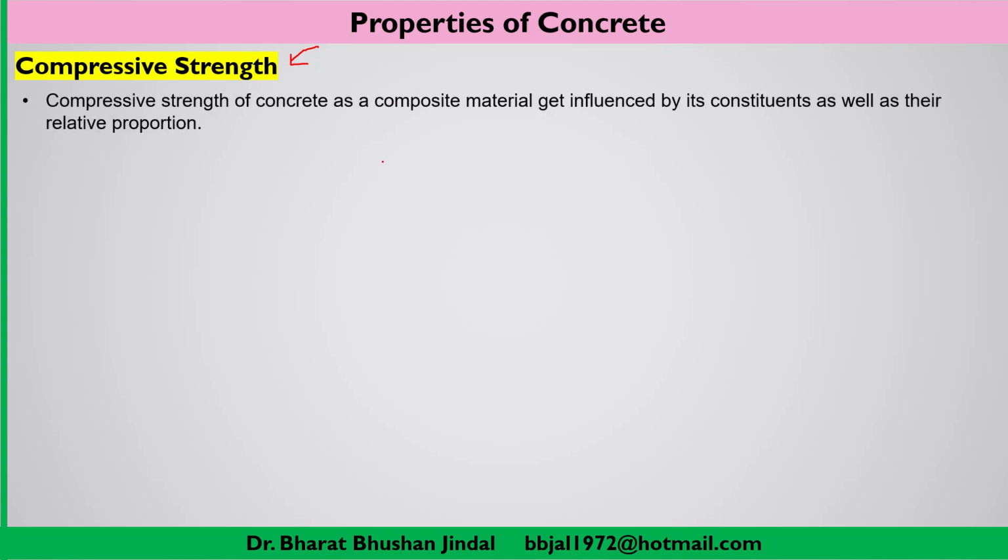First of all, let us understand this compressive strength of concrete. Because concrete is a composite material, it will get influenced by the constituent materials. That means the ingredients. So compressive strength will directly depend on the ingredients, and not only the ingredients but also their relative proportion will influence the compressive strength of the concrete.